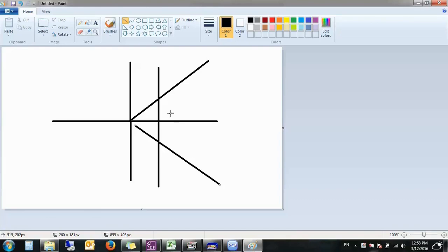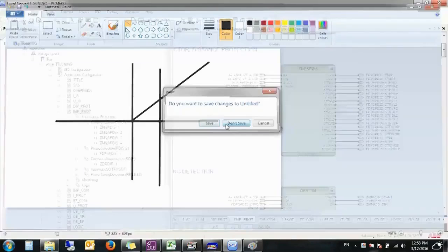In the microcontroller, you have another setting for undervoltage for the load blinder. You calculated the load blinder based on it being 0.8 of the UN at 150 volts. It said, okay, how do I know if this is a fault voltage or load blinder? It told you that if the voltage drops below a certain threshold, e.g. 0.4 of the UN, it is impossible under normal load conditions. The voltage cannot reach 40% of the UN. Therefore, if your voltage is less than 40% of the UN, I will consider this area as a voltage block on the load blinder and will not consider the load blinder to be working at all. It will operate with the normal zone timing.